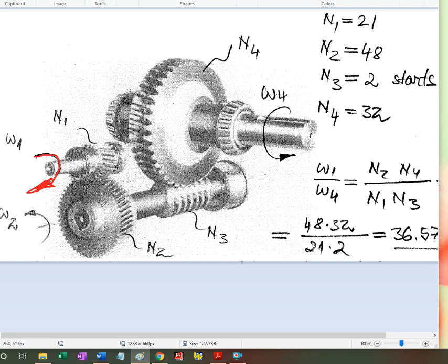So we want to know, firstly, what is the direction of rotation? That doesn't come out from calculations like before because the shafts rotate in different planes. If I change the angle of the worm and the wheel, of course, they need to match. One is negative, the other one is positive, in order to have meshing about perpendicular axes.